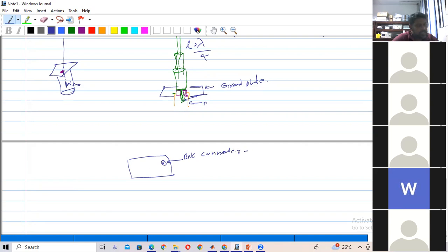Can you remember the impedance of a BNC connector? In our oscilloscope also we have BNC connectors, no? What is the impedance of a BNC connector? It can be 75 or 50 ohm. But the SMA connector has only 50 ohm. Try to remember this connector type; you should be able to identify it.